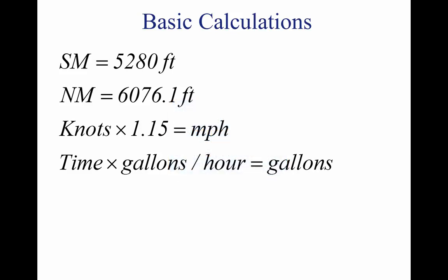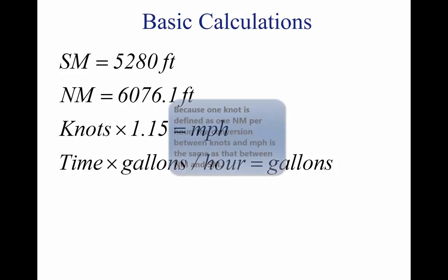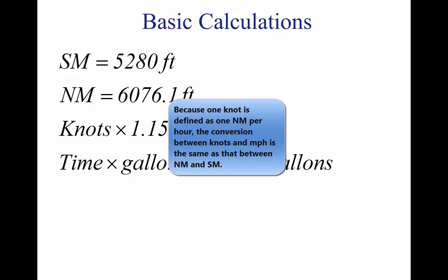However, airspeed indicators in some aircraft are calibrated in miles per hour, although many are now calibrated in both miles per hour and knots. Pilots therefore should learn to convert wind speeds that are reported in knots to miles per hour. A knot is 1 nautical mile per hour, nmph.